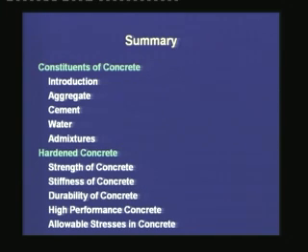and the tensile strength is usually measured by 2 types of tests. The flexural tensile strength and the splitting tensile strength are calculated from flexure tests and the cylinder tests, as I showed earlier. The tensile strength can also be calculated from direct tensile tests, but those are relatively difficult to perform.